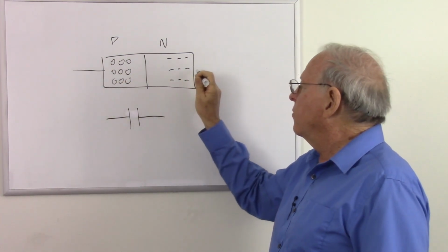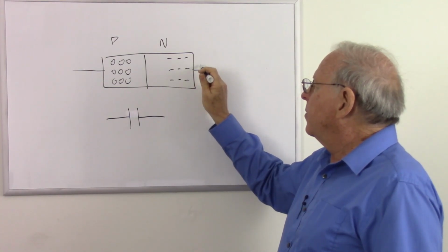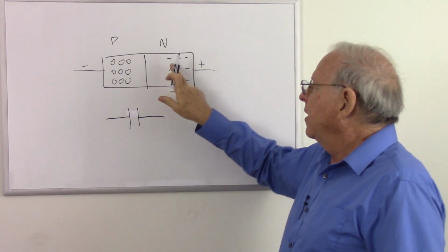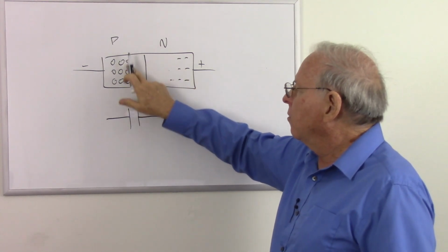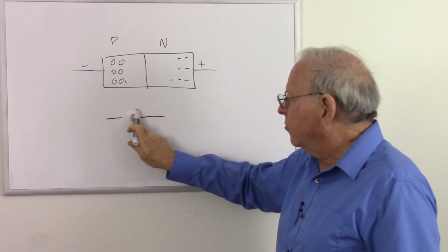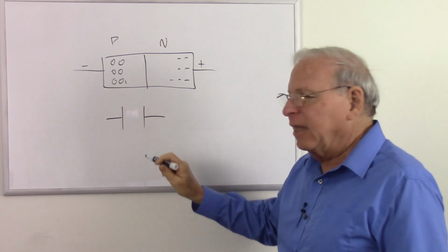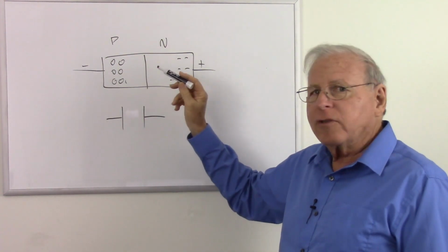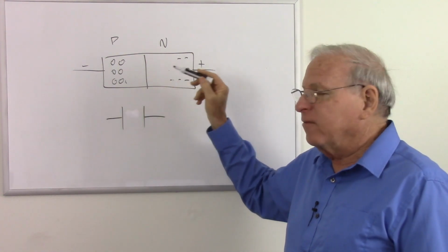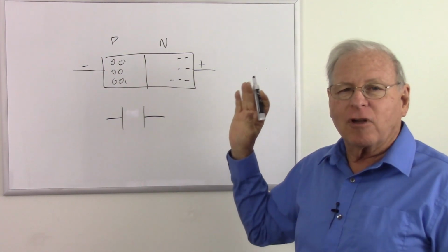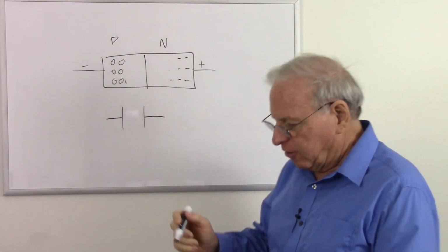What happens if we reverse bias it? Remember, if we put positive to the N side and negative to the P side, that makes the depletion region grow larger. So that's like making the capacitor have more distance between the conducting plates, which will decrease the capacitance. So can we use a reverse bias diode as a voltage controlled variable capacitor? Yes, we can. We have diodes optimized for that called varactor diodes.